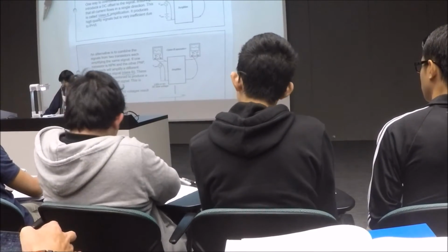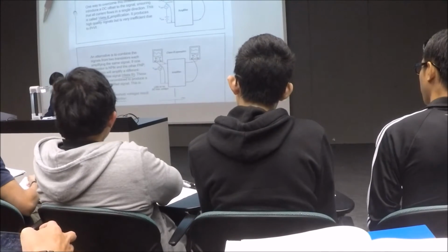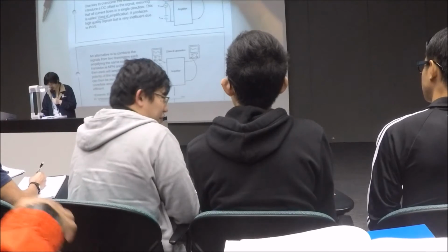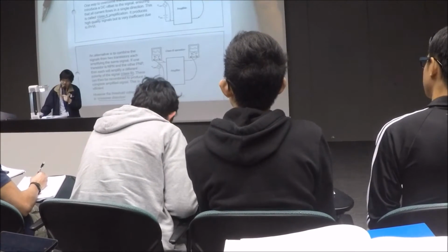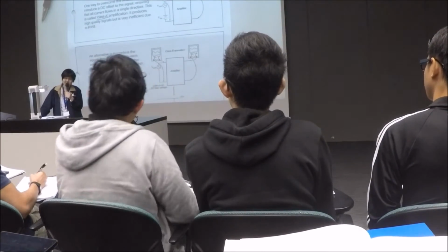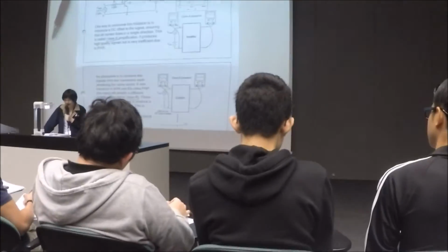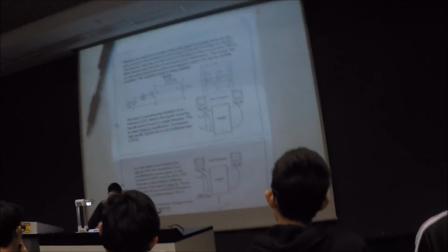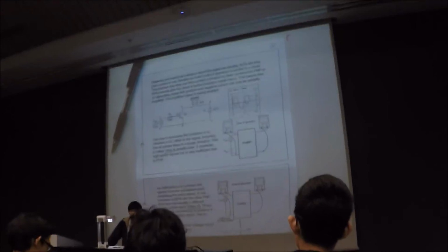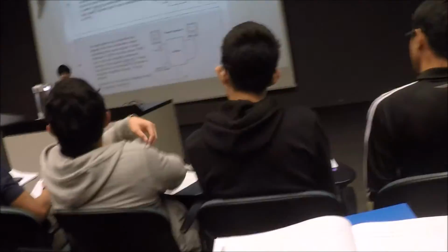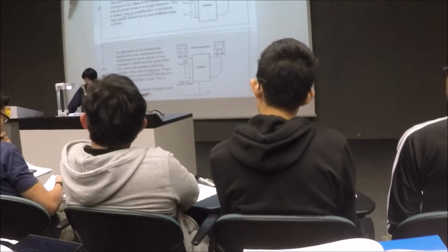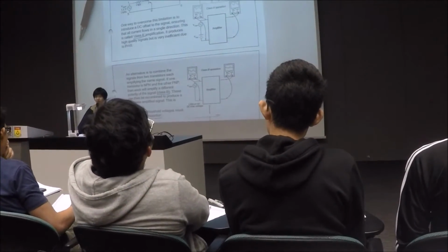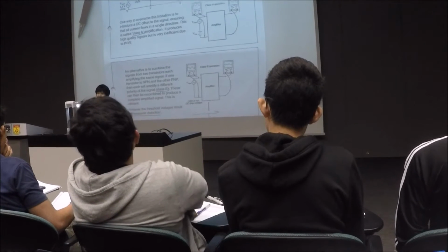So if you have your configuration this way, and your input is no longer a DC power supply but AC, it will have half the waveform running in the reverse direction. So in this way, your BJT will have current in half of the time.